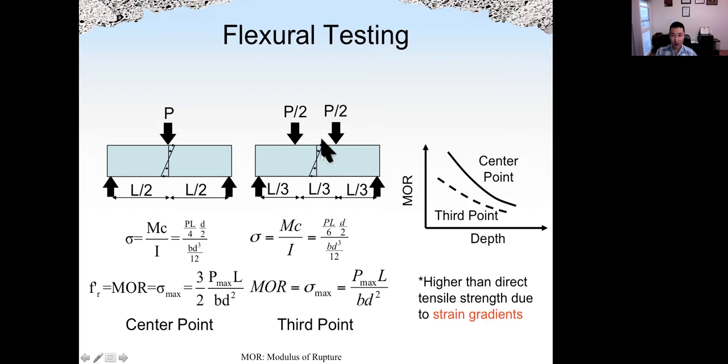Because the stress level along the cross section is very different. In the middle part, it is 0. The highest tension is in the bottom part, and the highest compression is the top part here. Okay,